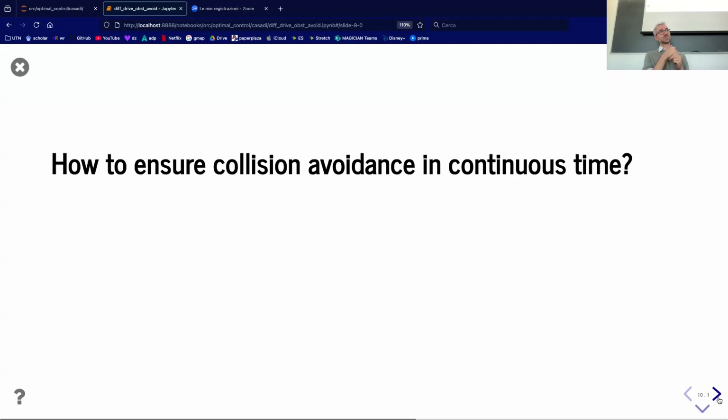Could I add more constraints, pair constraints, to the solver? Yeah, that's a third option. So you could maintain the same time step, so the same number of decision variables. You could just add extra constraints to say that you want the average state between time k and time k+1 to be collision free. So that is a bit like decreasing the time step, but without paying all the price of increasing the number of decision variables. So it's a bit better maybe.